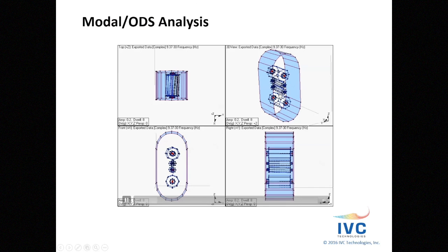Here you've got a typical roll stack, and you can see where the work rolls on the drive side are actually scissoring together. So if I'm running product through this mill, it's going to pinch the product at a periodic frequency that then equates to a quality defect. Again, it's another type of test, but it's something I have to take into account up front before I ever get to the point of hitting the go button to record data.